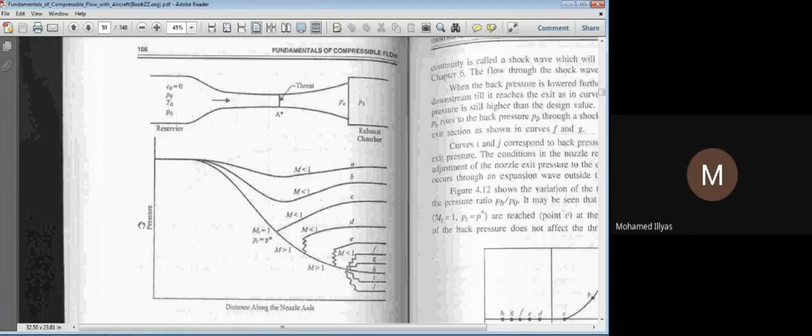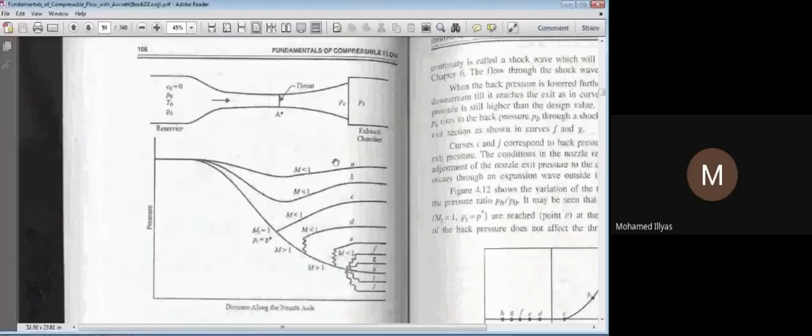they observed the pressure variation along the nozzle. You have a convergent shape, you have a divergent shape here. Okay, so they obtained the different curves here. So you see, for one position of the valve, just slightly opened, you can assume. So there is a decrease in pressure, correct? Up to this decrease in pressure. So that means an increase in velocity, because pressure and velocity are inversely related. So there is a decrease in pressure, so a corresponding increase in velocity.